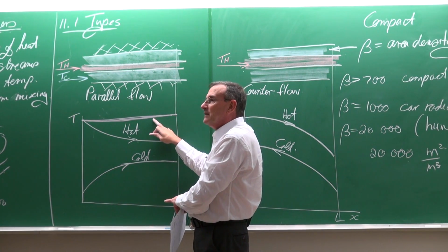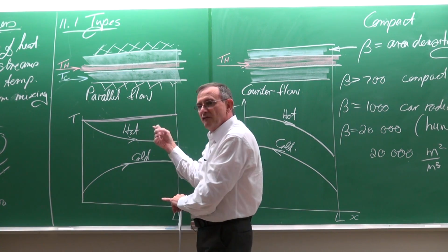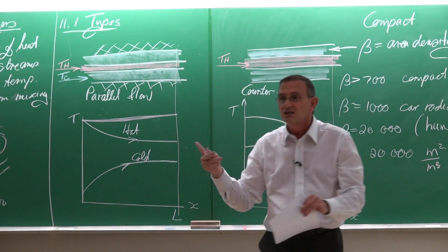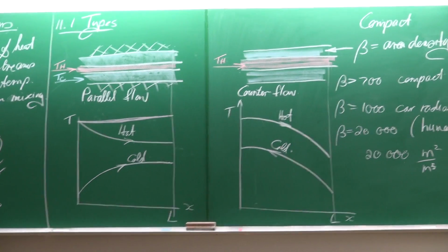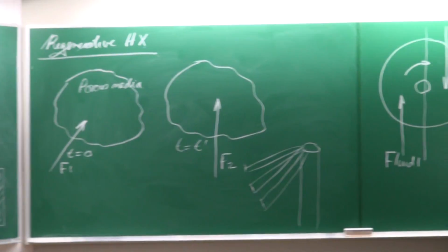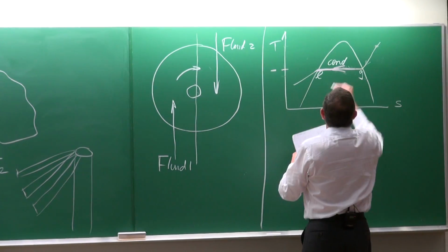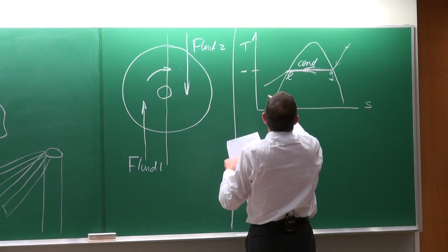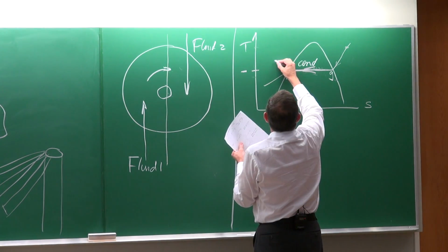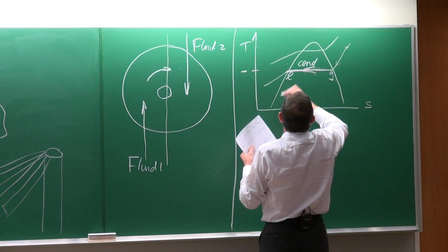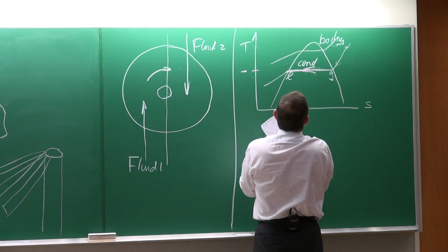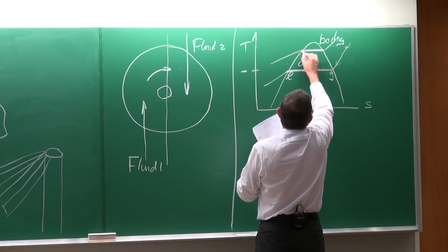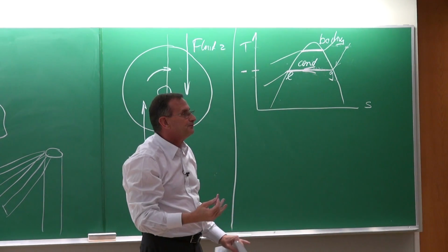So it will mean that the best types of heat exchangers, the most efficient types of heat exchangers, would be heat exchangers where on the one side you have condensation, okay, or boiling or evaporation. So that would be for condensation. For boiling, I'm just going to obviously, yeah, let's rather draw it there. So for boiling, it's going to be there like that. And again, the temperature is going to remain constant.